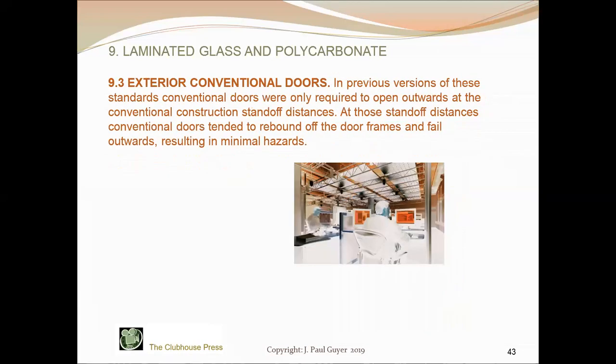With regard to exterior conventional doors, in previous versions of these standards, conventional doors were only required to open outwards at the conventional construction standoff distances. At those standoff distances, conventional doors tended to rebound off the door frames and fail outwards, resulting in minimal hazards. With the reductions in conventional construction standoff distances, that assumption is no longer valid.